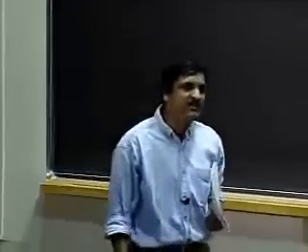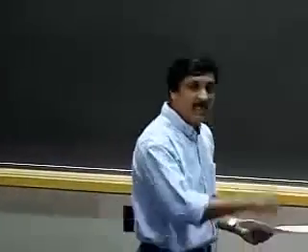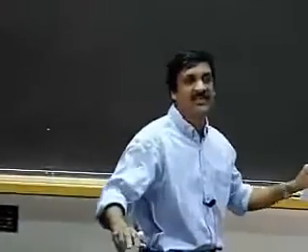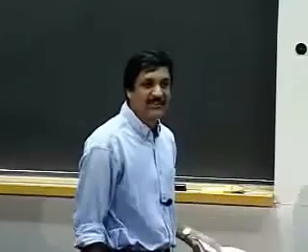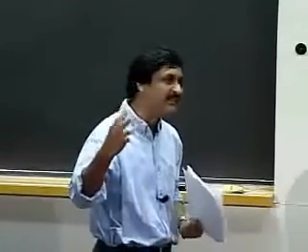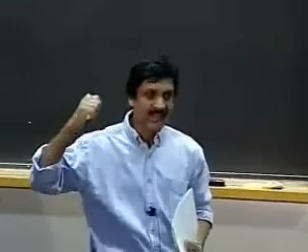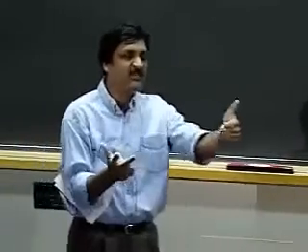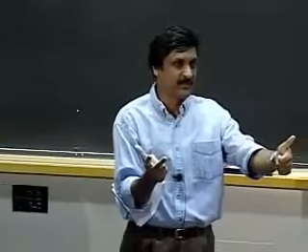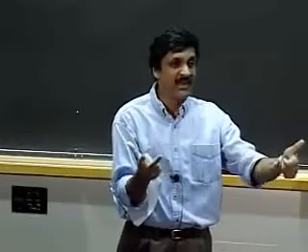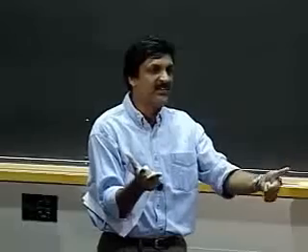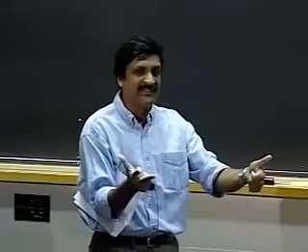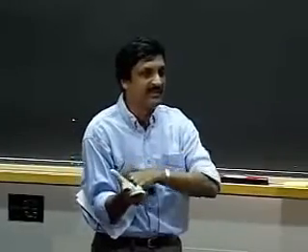Again, as I pointed out to you at the beginning of this lecture, no new foundations today, no new theories, no new disciplines, no new laws. We're just going to take what we've learned: three simple things, infinite gain, infinite input resistance, zero output resistance, plus this new thing, V plus equals V minus. Armed with just those four principles, we're going to charge ahead and analyze a bunch of circuits. It's a lecture on pure applications today.